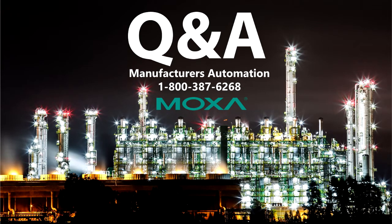Simply put, resistive is simple. It's more simplistic. It's less advanced. It's oftentimes less desirable, but it's required a lot of times in industrial networks because people are wearing gloves, for example, or if they're not, it's a dirty environment. It's a rough environment. You can't use a capacitive touchscreen. Simply put, for that reason.